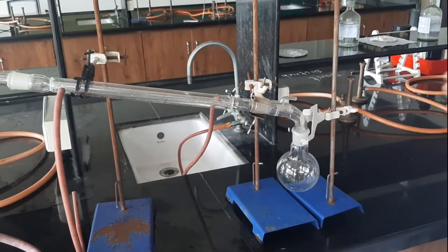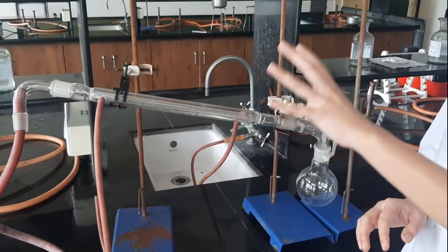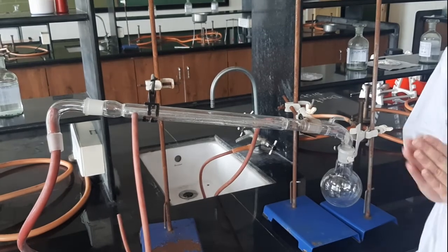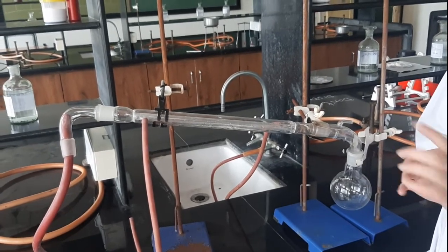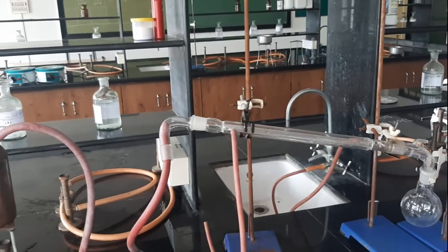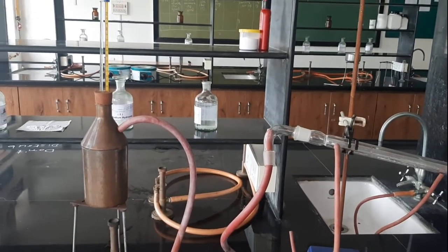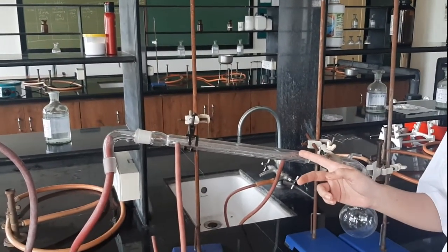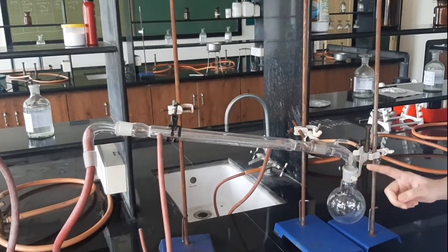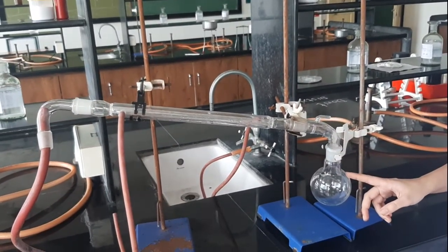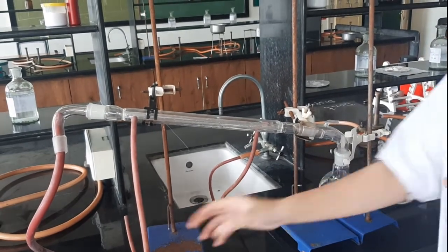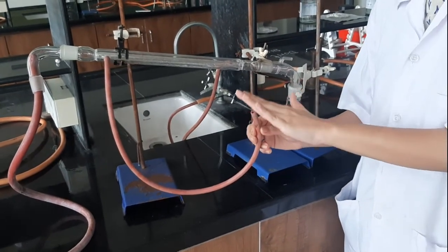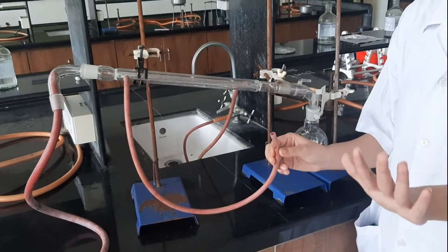Now the procedure for this experiment is, first we have installed all the setup. So what are we going to do now? First we will start the burner. The steam will be generated. We are going to measure the temperature of the steam. Once the steam comes into this condenser and starts to condense, after we receive one drop of the condensate, we are going to start collecting the water. This is for counter current. Then we will start collecting the water. We will carry out this process for 5 minutes.